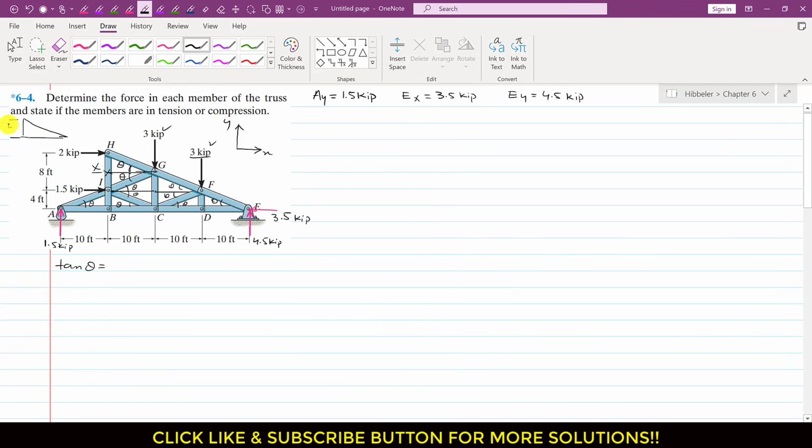This height is 4 feet, since we are considering the half of this, and this is 10 feet. So tan theta will be 4 divided by 10, and theta will be equal to tan inverse of 4 divided by 10. This comes out to be 21.80. So let me write that theta here: this theta is 21.80 degrees.